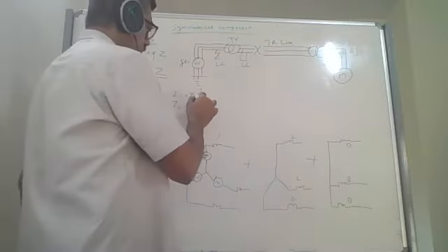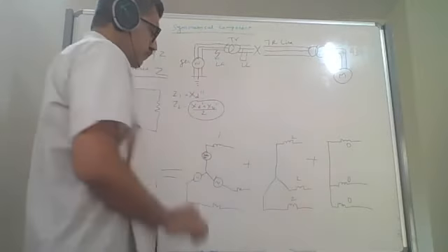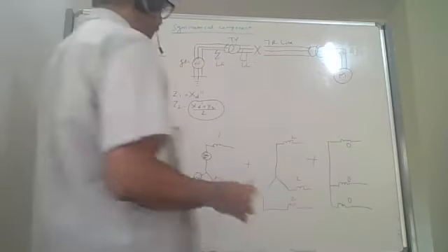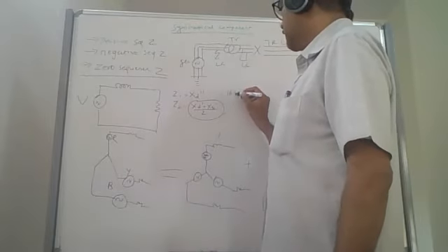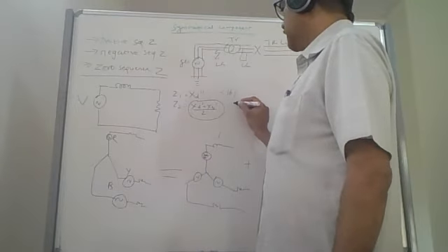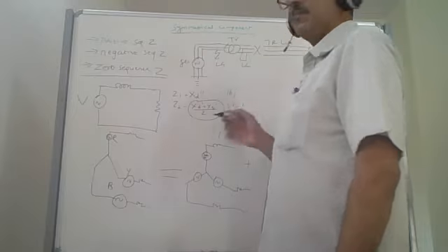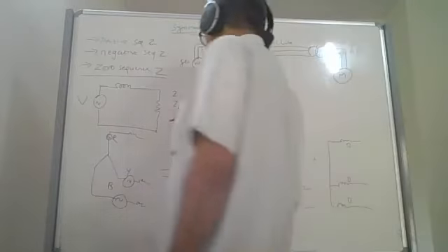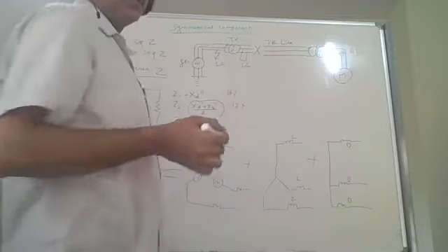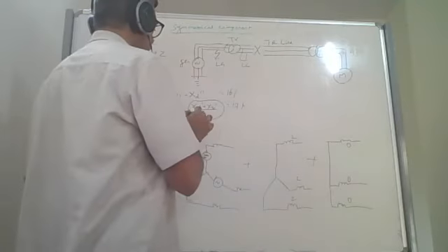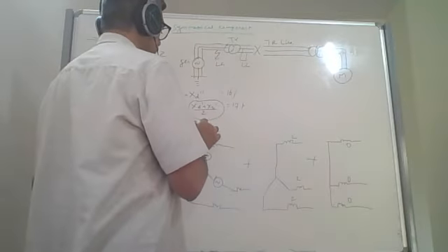This particular thing I will check and let you know. But what I found last time, one generator positive sequence was like 16%, negative sequence was like 17% or something. And zero sequence, the generator data sheet will give it. It will be something like 8% or something.